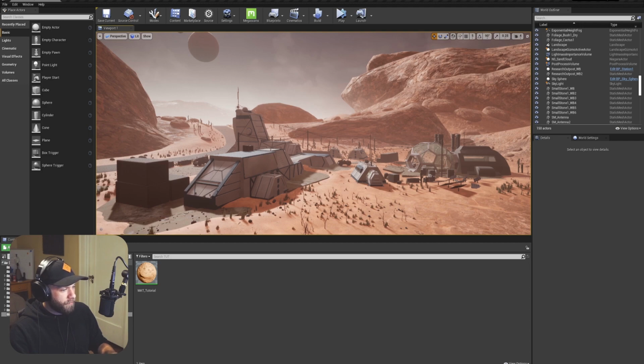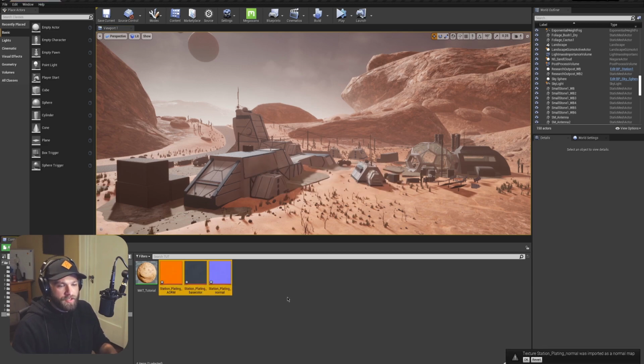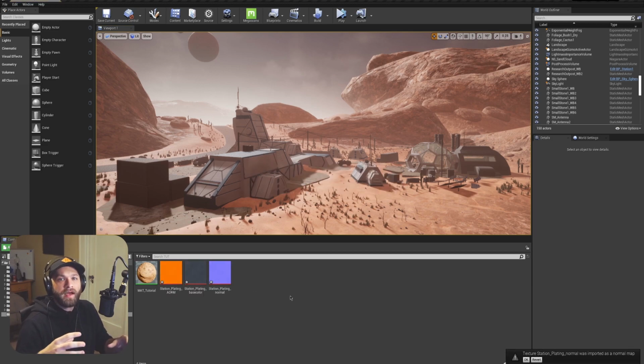In my case, I have some textures here that I've created in Substance Designer, and I'm working with a packed map system. So instead of having, for example, 3 2K textures for Roughness, Metalness, and Ambient Occlusion, I have one packed texture that is still a 2K texture, but it has all 3 of those in the RG and B channels, and I even have a 4th cavity mask that I was using in the alpha channel.